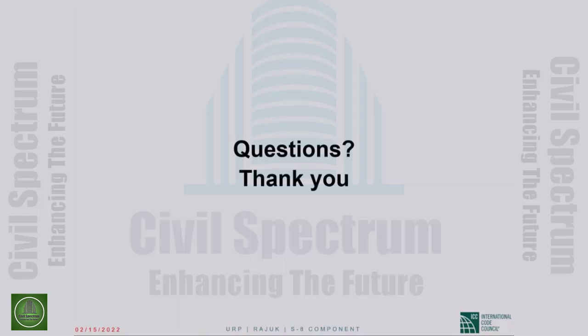Should we consider stiffness modifier? Okay, let me rephrase this, Dr. Ghosh. Should we consider stiffness modifier only when response spectrum analysis is required? The basic question is, should we use the cracked section properties only when dynamic analysis is required, or every time? No. The modeling section applies to static as well as dynamic analysis. This is very basic. The cracked section properties always have to be considered.